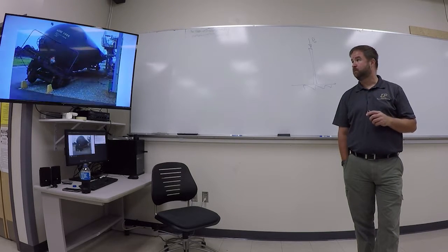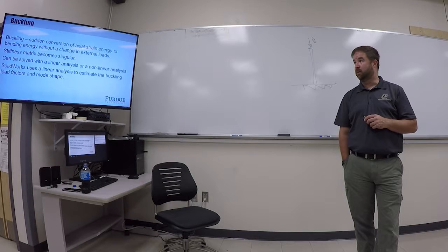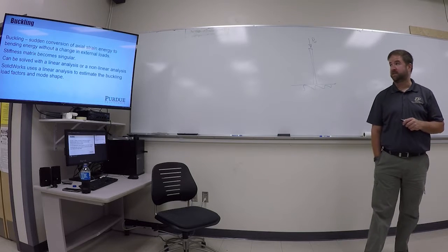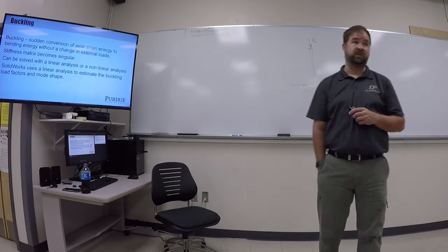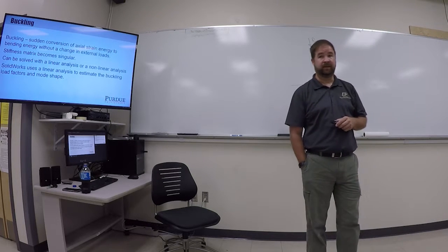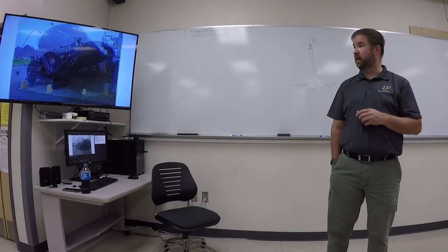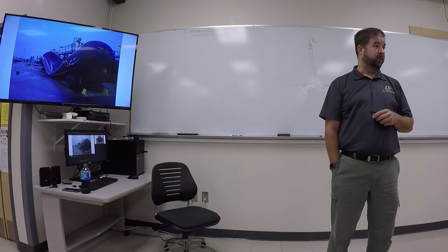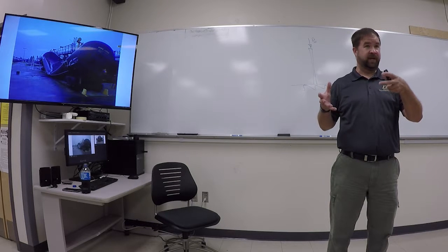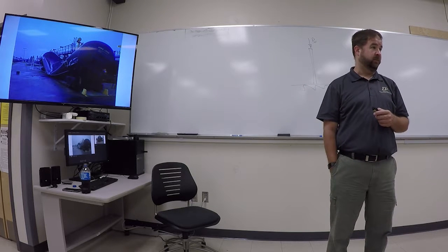Okay, so I have a little bit of information here. Here's a more rigid definition of buckling: the sudden conversion of axial strain energy to bending energy without a change in external loads. And the dramatic thing about buckling is that it happens suddenly and without a lot of warning. It's a catastrophic collapse. So it would have been really fun to have a video of this thing going. Probably it was sitting there, and one second it was completely intact, and the next second you heard this crashing noise, and then it shriveled up and sucked in on itself.